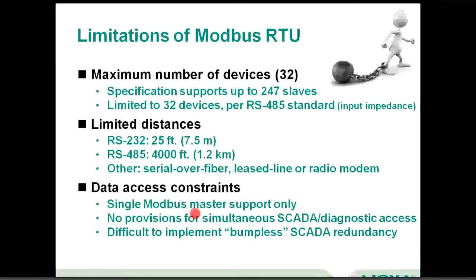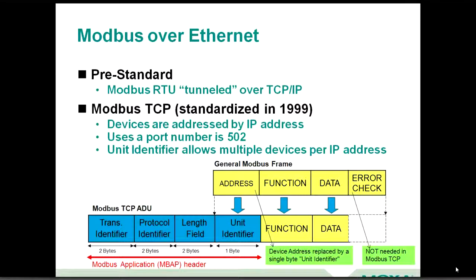There's no provisions for doing remote diagnostics at the same time your SCADA system's running. And if you want to have a real robust system and have the ability to have multiple SCADA servers, it's really a challenge to architect those types of systems without doing some difficult things when you're working with direct serial connections over RS-485. So with that, let's take a little look here at how some of that's been solved by moving to Ethernet. And let's also talk about some of the extensions that were done.